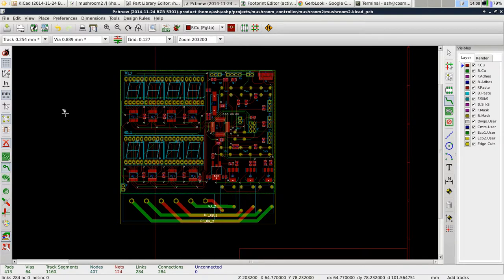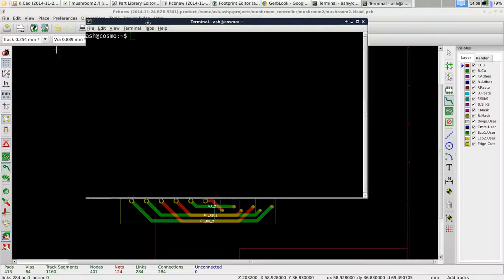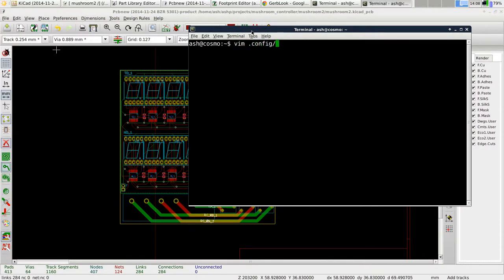You might have a problem with the default library tables, but when I do a tutorial, I will make sure I show how you can get the default libraries and stuff. But briefly, in case you get some errors when you install it, because you might get this anyway depending on what operating system you install it on: what Kicad stores in the library lookup is something called the FP lib table. There's a kind of machine-wide one somewhere, like user local share Kicad FP lib table or something.